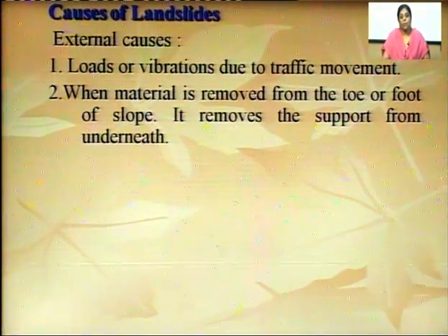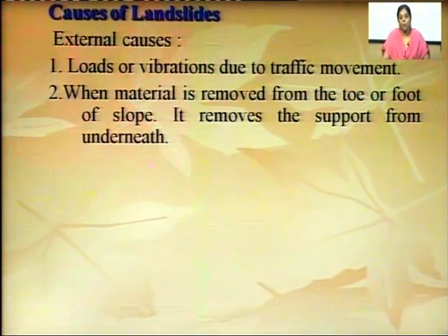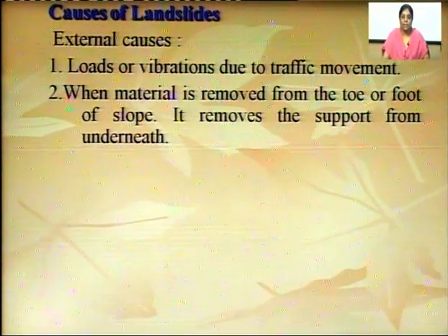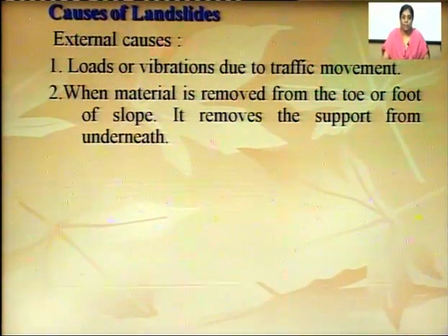When material is removed from the toe or the foot of the slope, it removes the support from underneath. So, when support is removed, the upper material is without support and the landslide occurs.